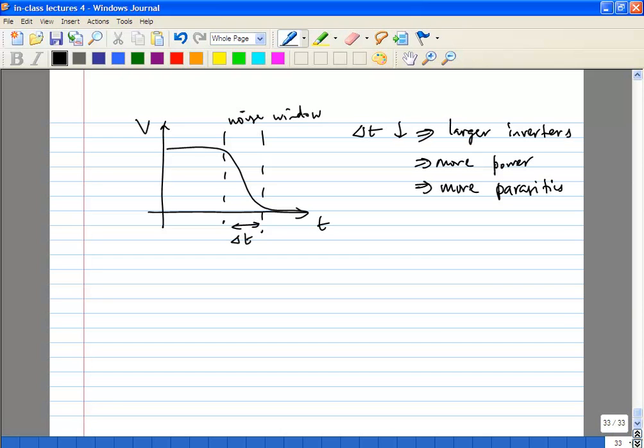So typically you deal with parasitics by increasing the number of stages. If you have too much capacitance, yes, definitely. So there is definitely an optimum number of stages, optimum power, and so on. You'll have to figure that out for any design. If you're given that you have to drive a certain capacitance, you'll have to figure that out by yourself.